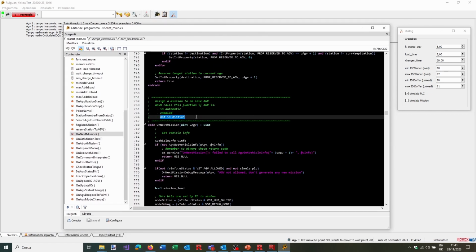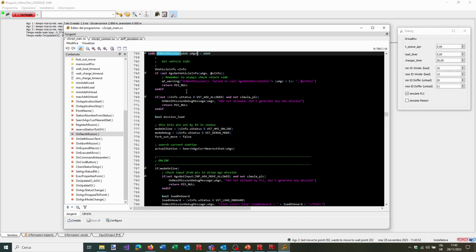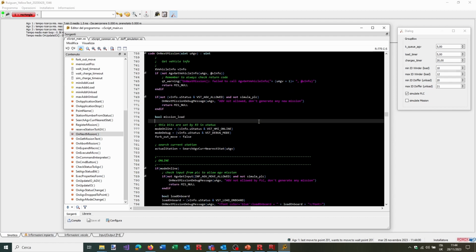And finally, you must, of course, not have another mission to do. While these three conditions are met, the AGV will automatically call this function, and then it's up to your code to dispatch to it the mission that's requested. You will see in the case of your plant what is the most important mission to do, if the current AGV is available, if the zone is not some kind of forbidden zone, and then the AGV will register a mission.